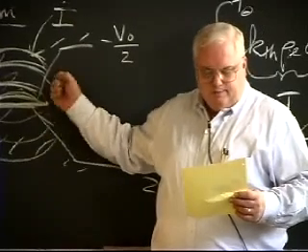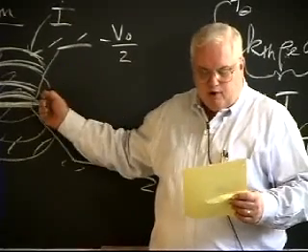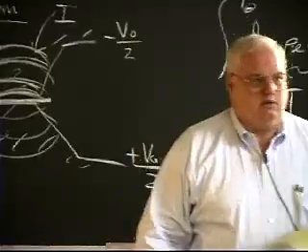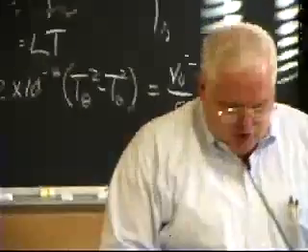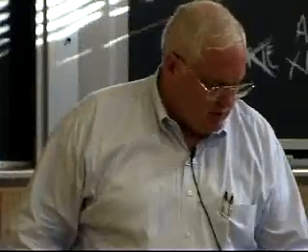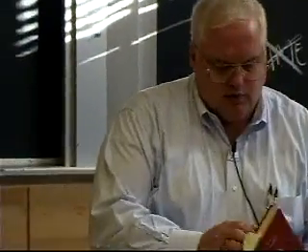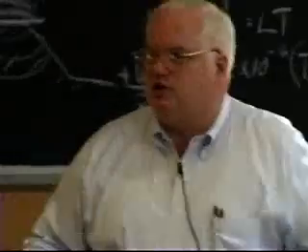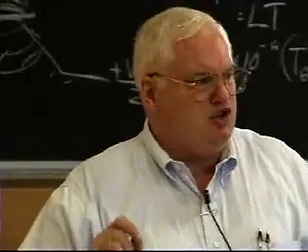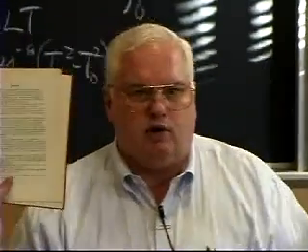And to boil copper, you only need 0.8 volts. For tungsten, you need 1.1 volts to melt and 2.1 volts to boil. Very low voltages create tremendous temperatures at these asperity contacts. And Table 10 in Ragnar's book is a table of melting and boiling voltages for electrical contacts.